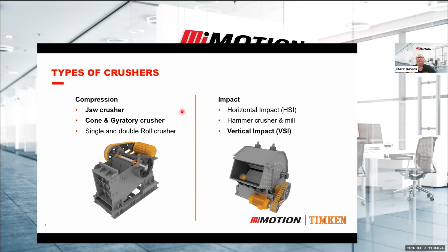It really depends on the type of rock that they're crushing, how hard it is, and also what type of ore, so the rock that is containing the target mineral or metal, or whether it's just a quarry that is crushing a rock down to a certain size for its different applications. But commonly we will see vertical impact crushers or VSI crushers in quarries especially. That's becoming quite common now as a very good tertiary or secondary crusher.